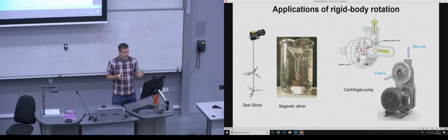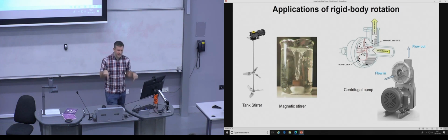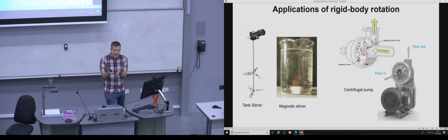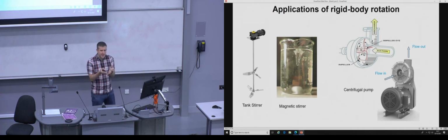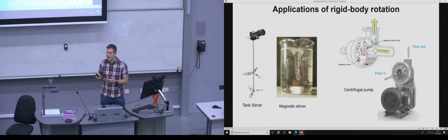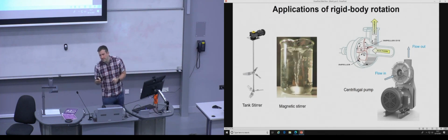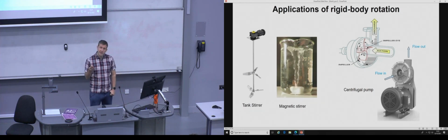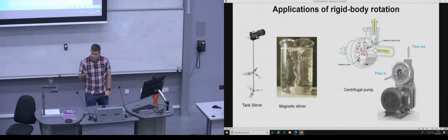What you see is the free surface forms this kind of parabolic dip down, which eventually touches the stirrer. You can see that while it's never actually stationary, the general shape of the fluid surface is more or less constant. It's always shaking. It takes a while to reach the point where it touches the bottom. But once it does so, we can assume that it is in a rigid body rotation state. Once we know that state has been reached, we can evaluate the distribution of pressures in the fluid using the same approach.